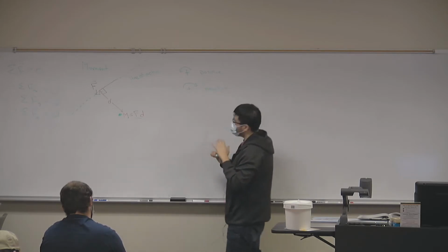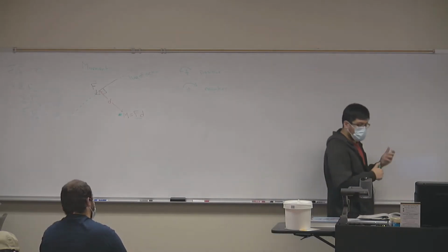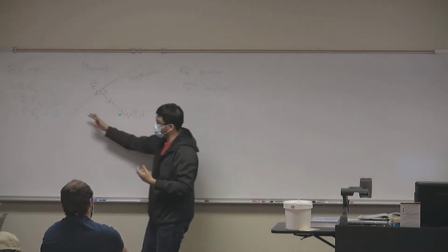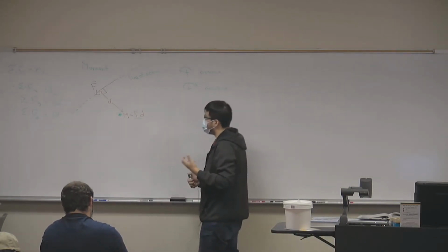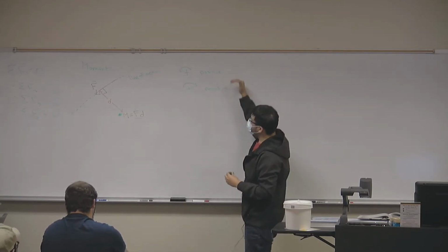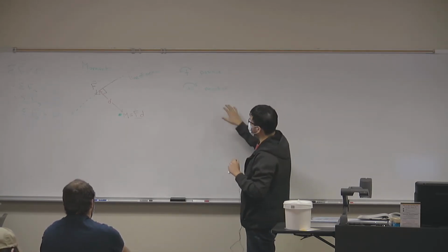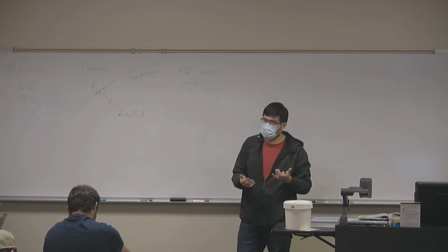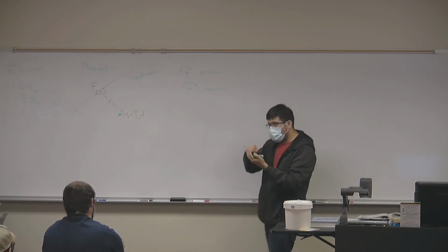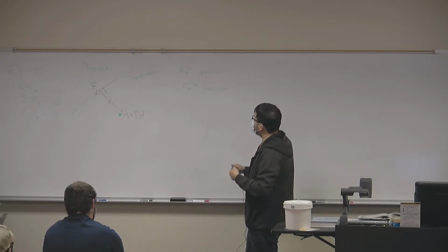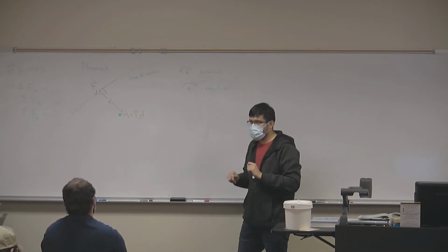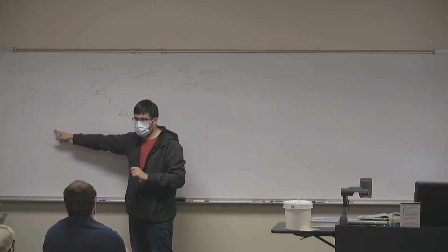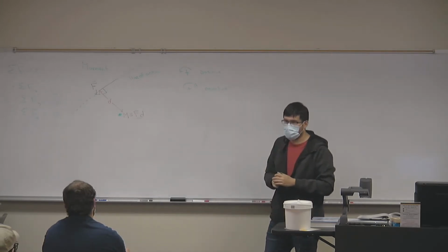Now, I don't want you to get too worried about memorizing these, because we're going to use moments in the context of equilibrium. And when we're dealing with equilibrium, it doesn't really matter which side you choose, as long as you have a consistent definition of what is positive and what is negative, your answer should be the same. In other words, if you're working on a problem on your homework and you accidentally flip these two terms, you should still get the right answer, because everything equals 0, right? So in the end, you should still get the correct answer for your moment.